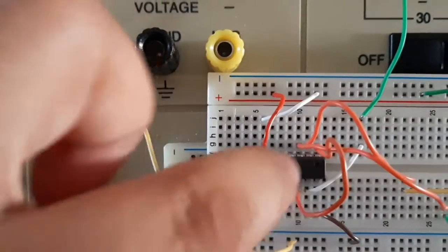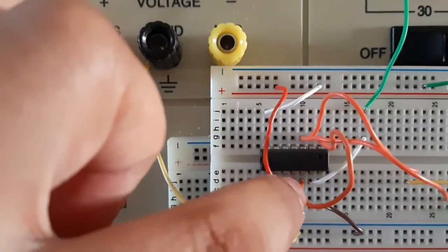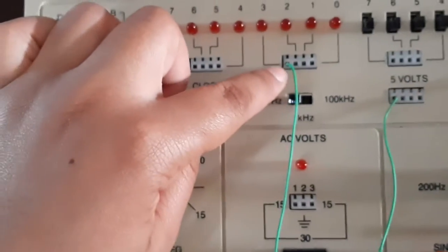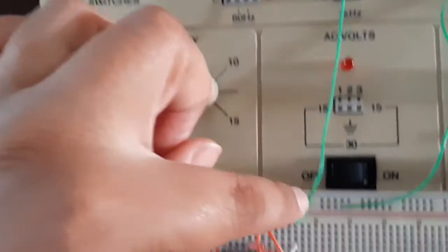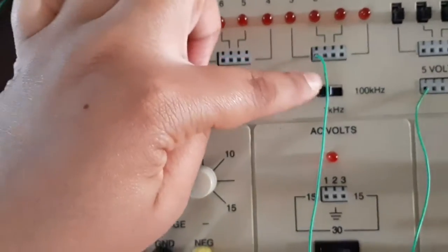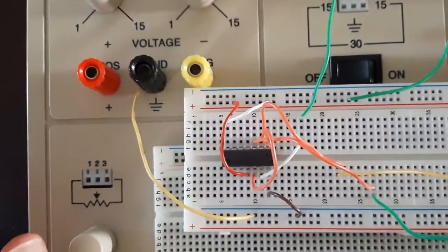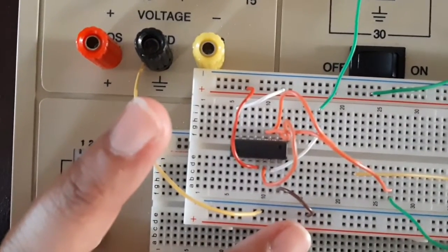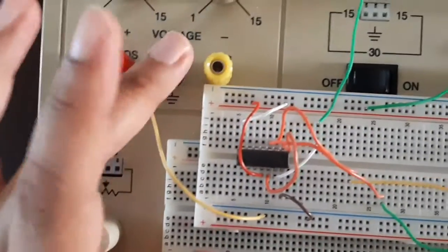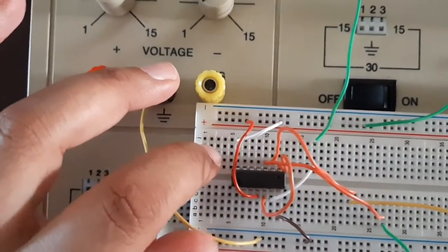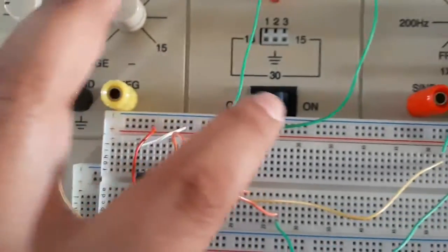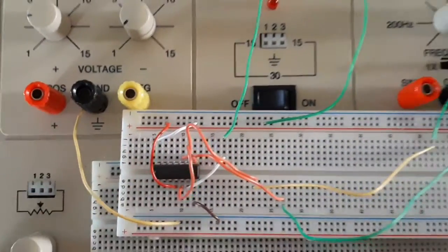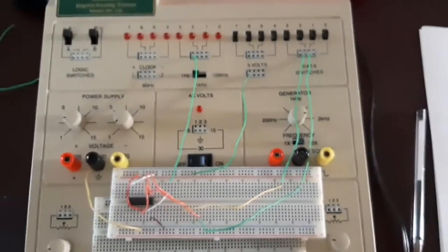And then pin 6, which is the output of this second exclusive OR gate, is bridged to LED number 3, just for the ease of being able to bridge it as close and as comfortably as possible. And then I have pin 7 connected to ground, and pin 14 connected to the 5-volt VCC, which is also connected to pin number 4 because it's one of the inputs. And that is how this circuit is wired.